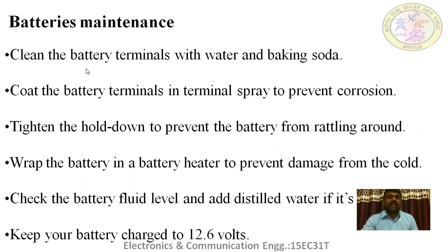There are basically majorly 6 maintenance points required to extend the lifetime of the battery. One is clean the battery terminals with water and baking soda.